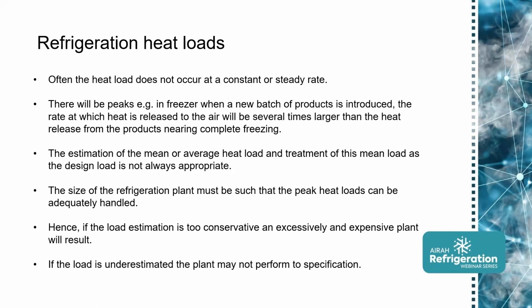The estimation of the mean or average heat load and the treatment of this mean load as a design load is not always appropriate. The size of the refrigeration must be such that the peak loads due to the warm product can be handled adequately. Hence, if the load is overestimated, an excessively expensive plant will result. On the other hand, if the load is underestimated, the plant may not perform to specification.